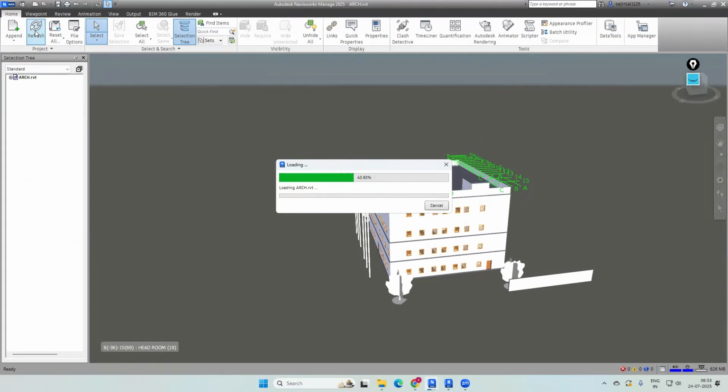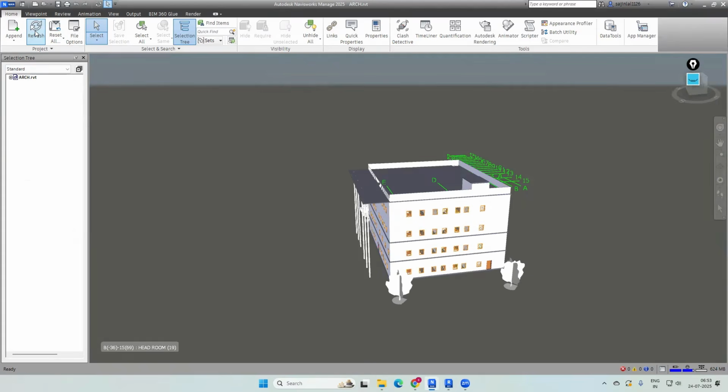It means in real time, the changes that we are doing in other computers on our real models will be witnessed in our Navisworks as well. So periodically, you can do that in a real scenario. And also, the changes I made in Revit, I can witness in Navisworks. If there are any changes I am doing in Navisworks, will they get reflected in Revit? Yes, there is an option called the switchback option.